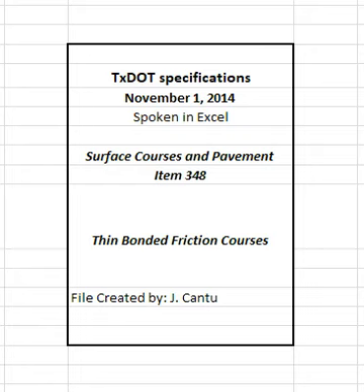4.4.2.1.18 JMF adjustments. If JMF adjustments are necessary to achieve the specified requirements, make the adjustments before beginning a new lot. The adjusted JMF must be provided to the engineer in writing before the start of a new lot, be numbered in sequence to the previous JMF, meet the mixture requirements in Table 8, and meet the master gradation and binder content limits shown in Table 7, and be within the operational tolerances of JMF2 listed in Table 9.